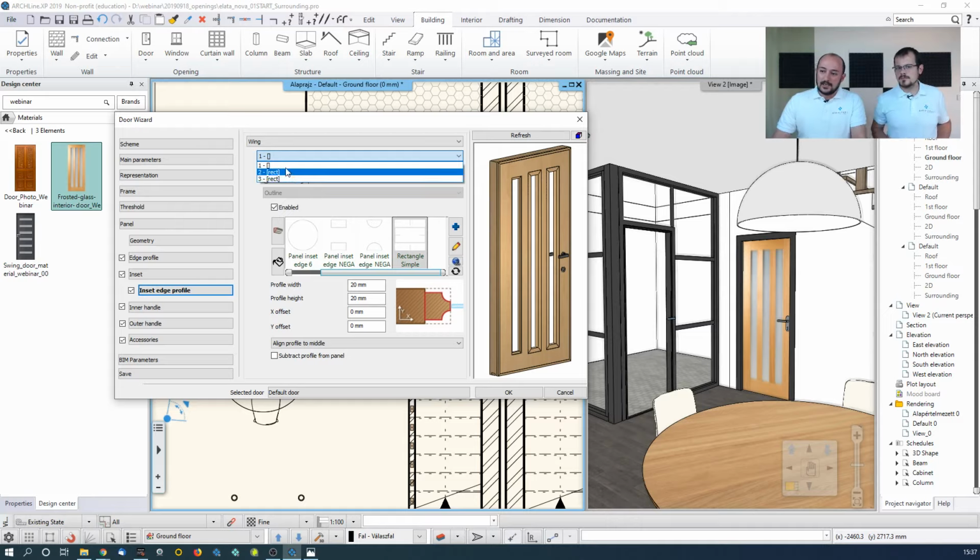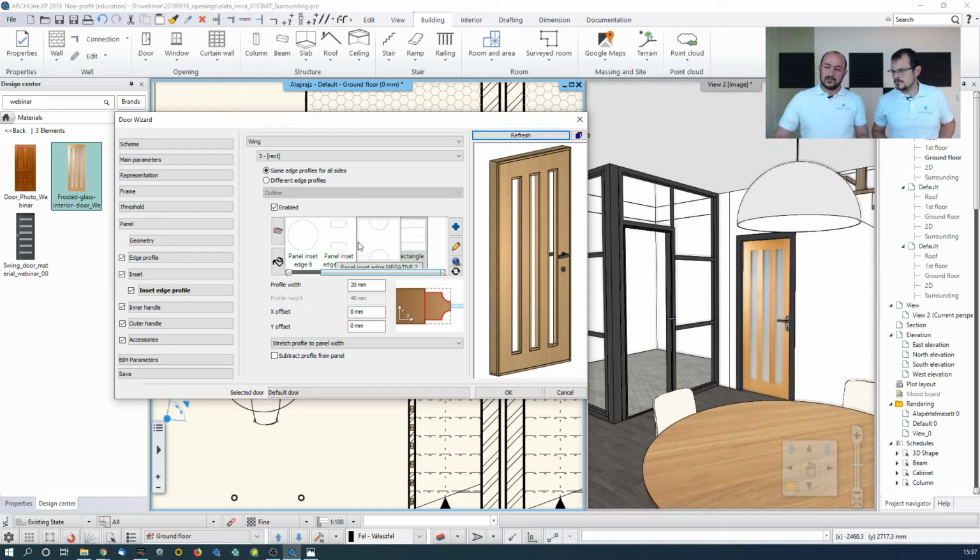So when I have the first one, I can see it has a specific profile value of 20. Then I apply the same thing here at the second one. It should be 20. And I go to the third one, and that should also be 20. And when I click on refresh, the software refreshes it with those settings. So all those little tiny details you can set up, even the materials and the cross sections. I just kept it simple for now, and then I will save it.